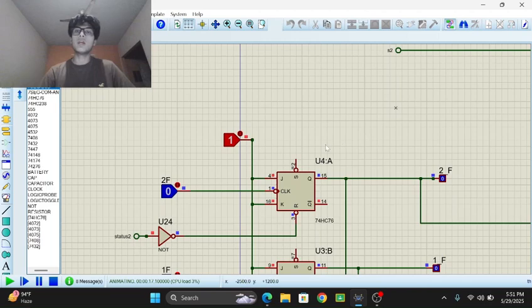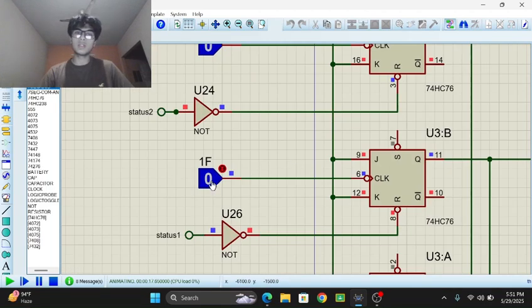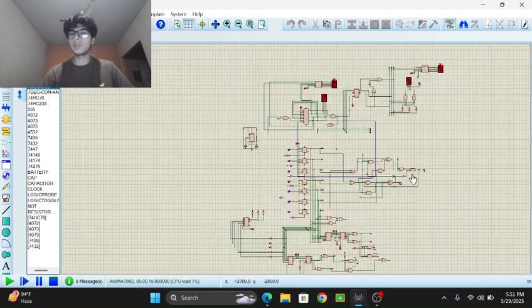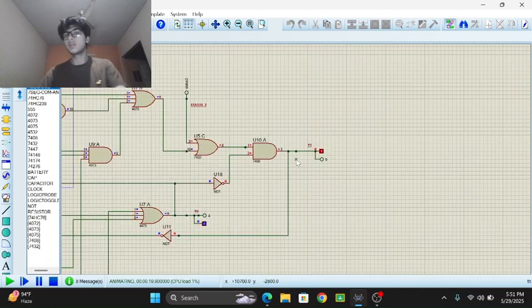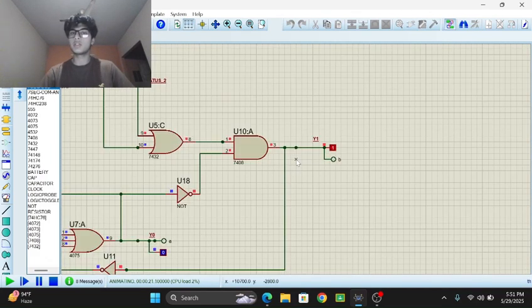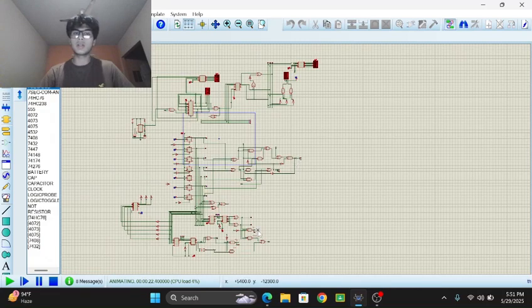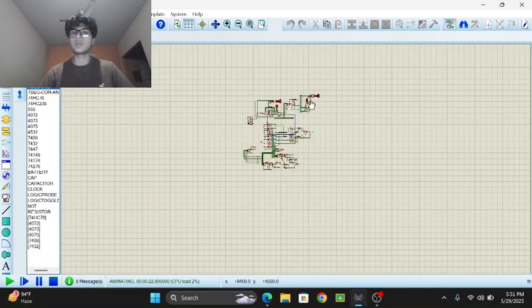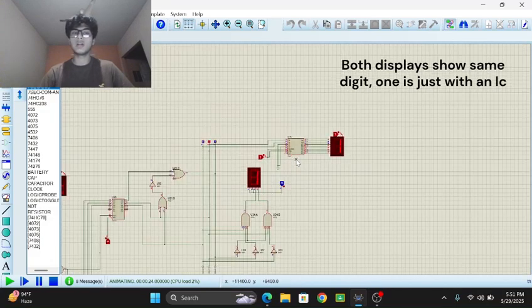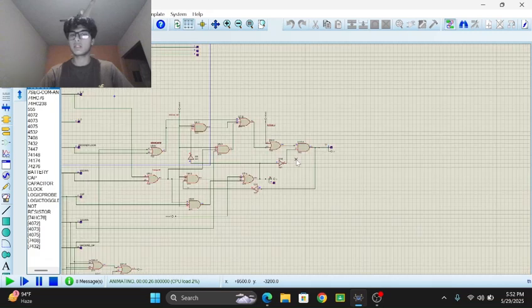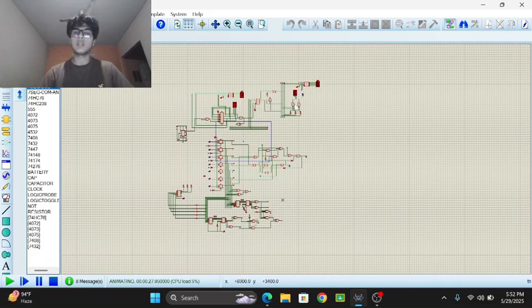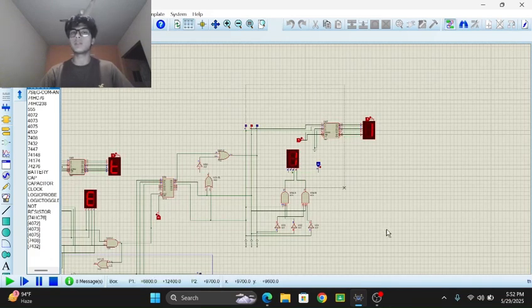And now if I want to move downwards into the first floor, a 10-second counter will then repeat, and as you can see, as we're moving downwards, the downwards directional control is now turned on, and the same with the priority encoder for downward direction as well. So now as you can see, since it was completed, now it's at the first floor. And this is how our elevator control system works, where it takes user's inputs, takes direction, takes lift position, and generates an output from it, which is able to be shown on a 7-segment display.